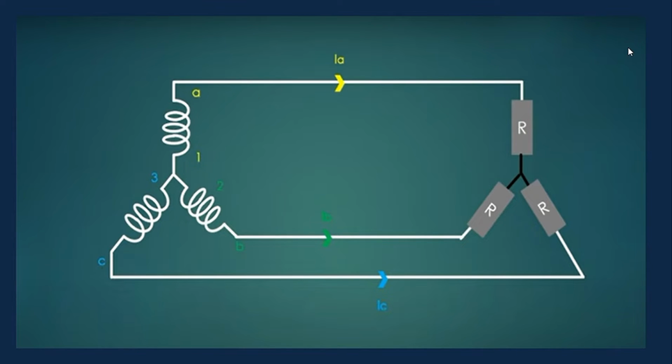If your load is not identical, then removing the neutral conductor can cause an unequal voltage across the load. In an ideal situation, where the load is equal, the current flowing through the neutral conductor is 0. The condition where the load is not equal is where a neutral must be provided. You might have heard people saying 3.5 core cable, where the 0.5 core is your neutral conductor.